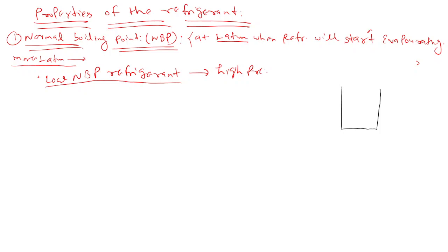Also remember these two lines, because actually only these two lines will be asked. High pressure refrigerants have low normal boiling point, and high normal boiling point refrigerants are the low pressure refrigerants.